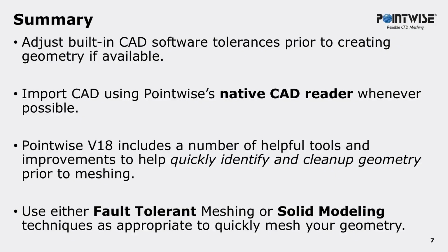In closing, if you have control over how the surfaces in your CAD are created, adjust the built-in tolerance of your CAD tool to something more suitable for use with CFD or FEA mesh generation. This will save users a lot of time during, if not eliminate entirely, the geometry cleanup step. Use the native CAD reader in Pointwise whenever possible, so that Pointwise has all of the information about your geometry when importing it into Pointwise.